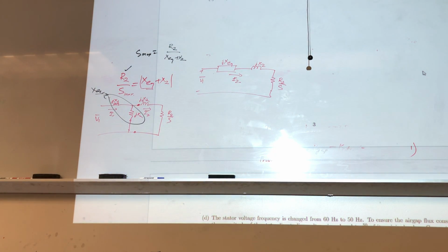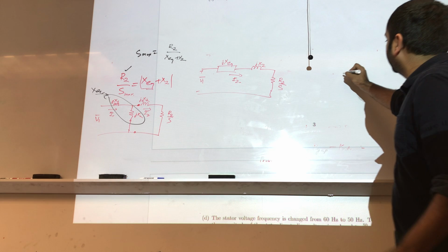Maximum torque happens when there's maximum power. So that means we previously managed to find the point at which it's max power. Yeah, exactly. Just something in the book that I saw, there's a different notation for S max T and S max P, which is why I thought there might be separate values. That's max power and that's max torque. But think about this. What is torque?